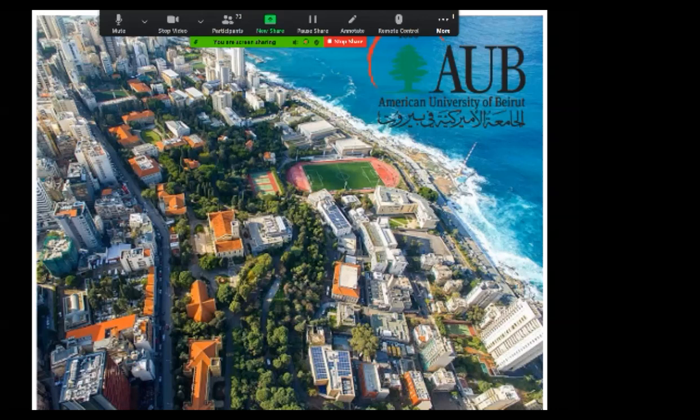I used a special axle, okay? And I tried just one axle, and it took me a bit more time. So I did apply the boundary conditions, but they were very far. I kept increasing the distance from the edge of the gear to the edge of the pavement until the stresses didn't reach the boundary anymore.